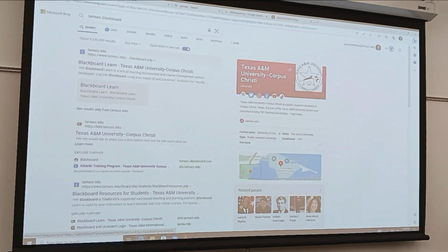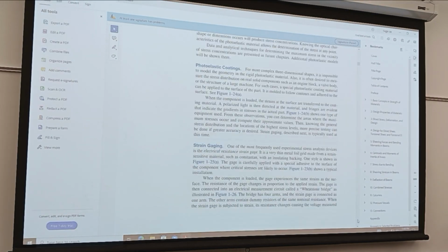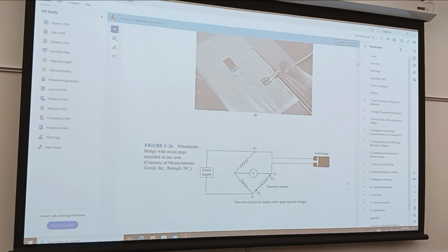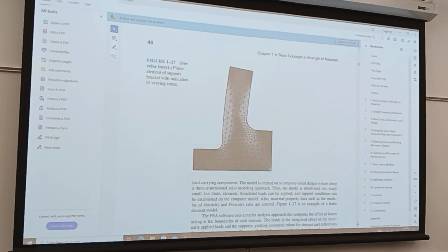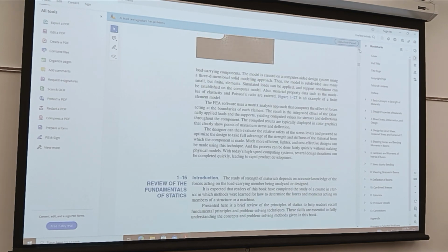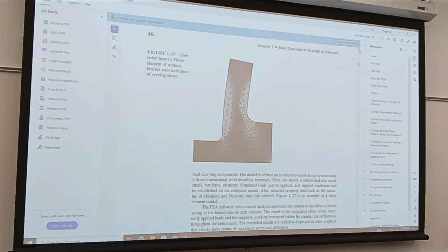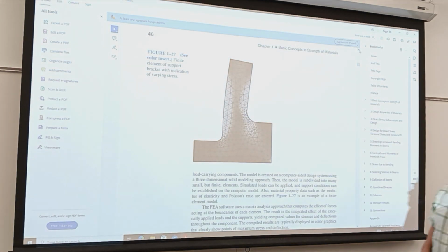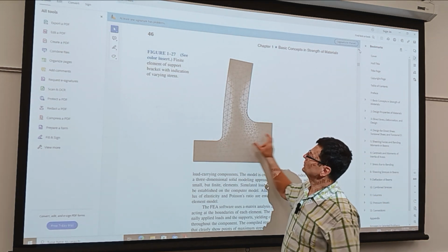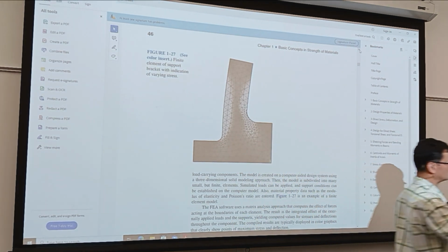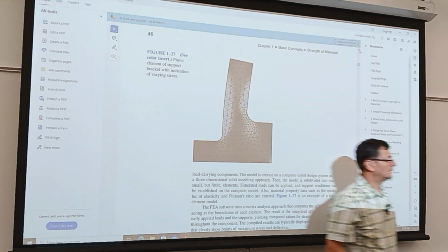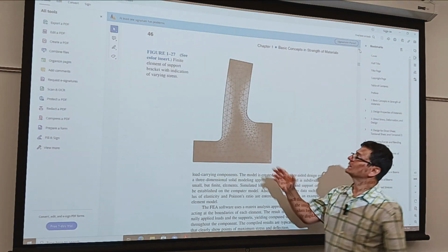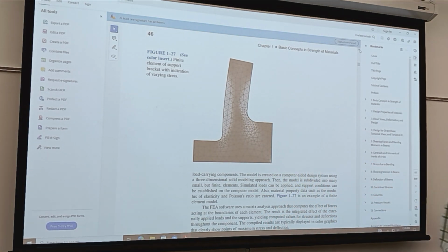Okay, so in strain gauges, or numerically, running experiments before you commit to a part. And the book doesn't mention it, but there are packages that allow what is called structural optimization. You define it as a parametric part with ranges that can change, say this dimension and this one, and maybe an angle, until for a given loading you get the minimum possible stresses.